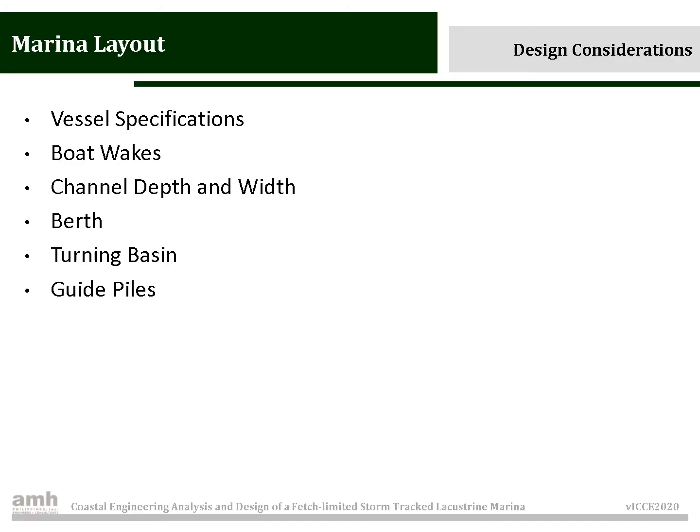Now we proceed with the marina layout. The design considerations for marina layout include the vessel specifications, boat wakes, channel depth and width, the berth requirements, turning basin dimensions, and the guide piles.